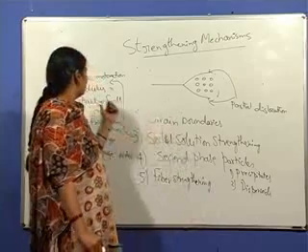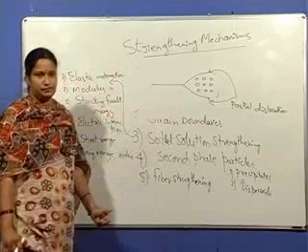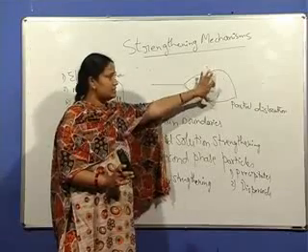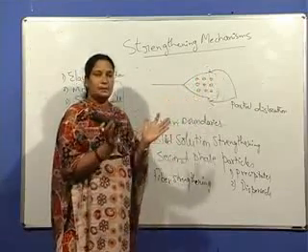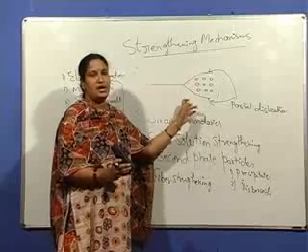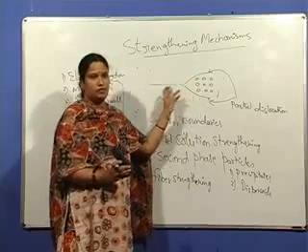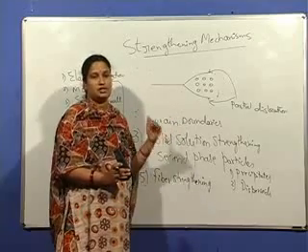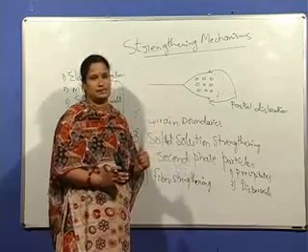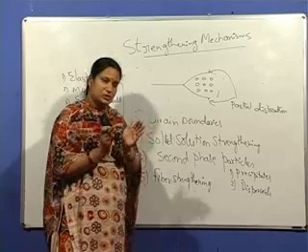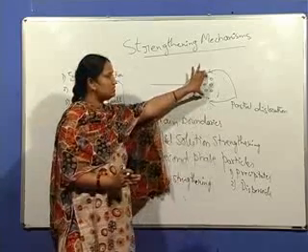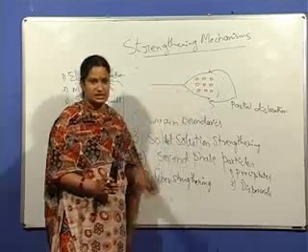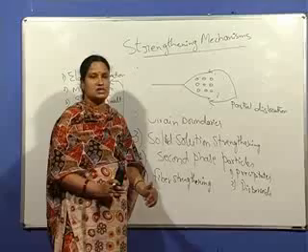So this is about stacking fault energy. The lower the stacking fault energy, the wider is this faulted region, with more separation between the partials, and it is very difficult for this stacking fault to move, thereby the strength of the material increases. If the stacking fault energy is very high, the two partials will be closer and the dislocation can move easily. It can cross slip easily.